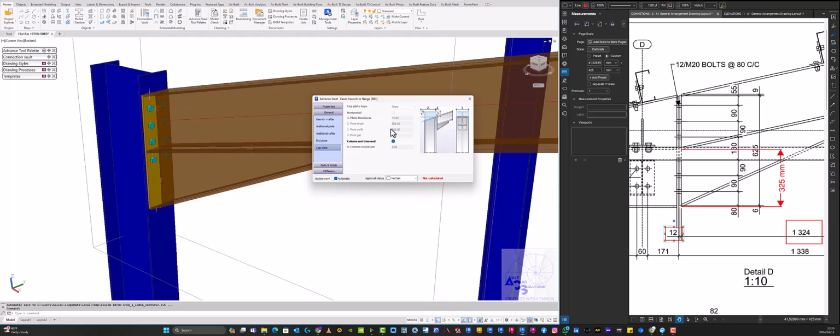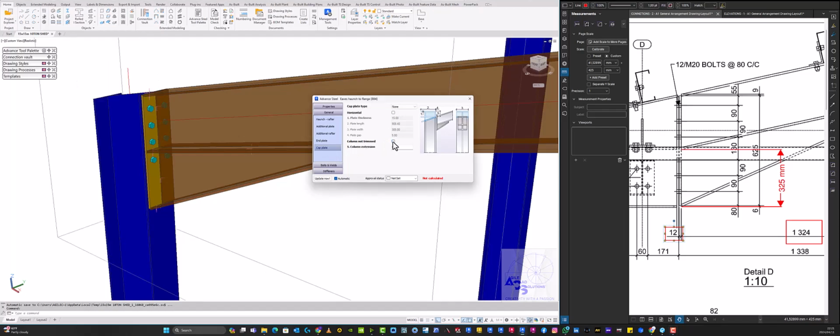Then we say cap plate. Cap plate confirmed, no trim. All right, we need this. We need this. We need this. Where do we sort this out? All right. Additional plate. This is not what we need. Additional rafter. This is not what we need. End plate. This is not what we need. Where, okay, our cap plate, why is it not highlighted? Okay, so all right, let's just uncheck this, and okay, this is what we need. So now it has been trimmed.